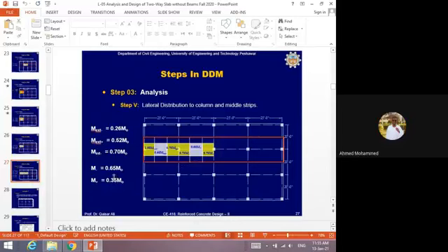If you count from the beginning, for the exterior, we will divide 100% of the exterior negative bending moment, and this is the exterior negative bending moment, 0.26. 26% of M naught, of the whole bending moment, will go to this exterior portion. Of this exterior negative bending moment, 100% will go to the column strip and 0% will go to the middle strip. Is this for positive or negative? This is for negative.